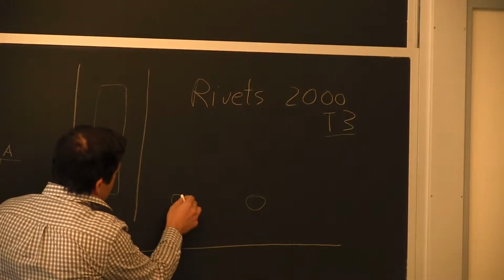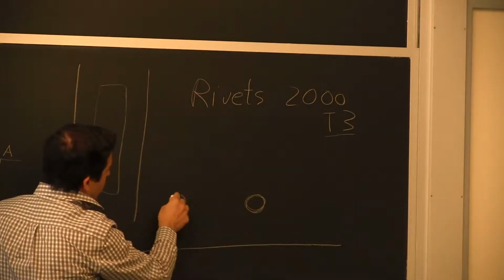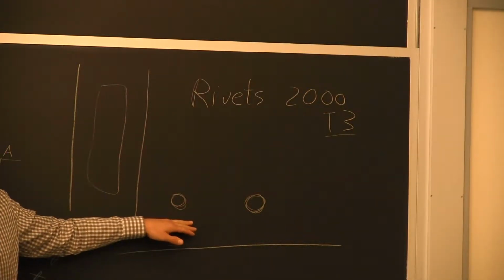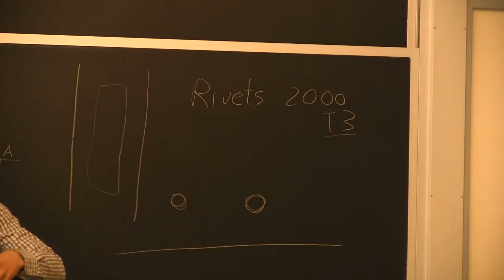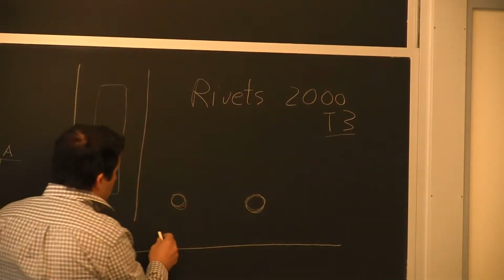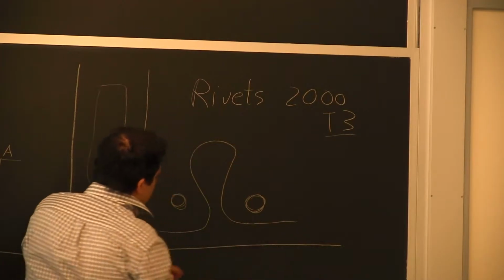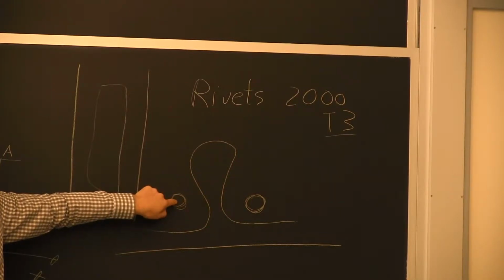If there's enough strain field, enough deformation going around the particles, the dislocation will feel it. It will realize it's coming into a zone where the crystal is not in the minimal energy configuration. It's going to be harder for the dislocation to reach the precipitate. And that's what happens when you start forming loops like this here, where the dislocation just goes right in between and just can't get right over the precipitate.